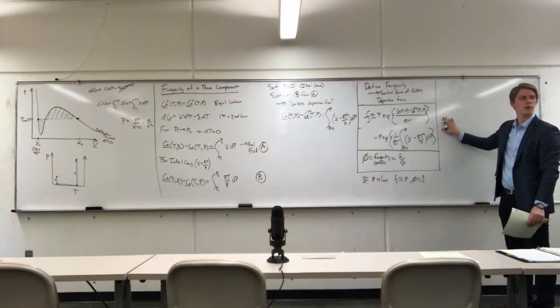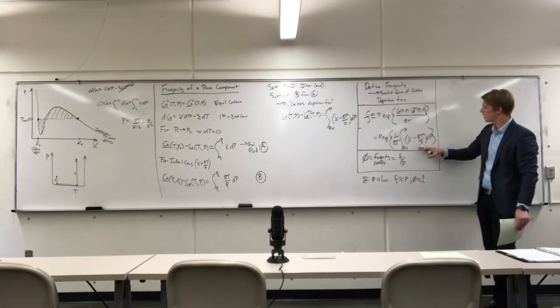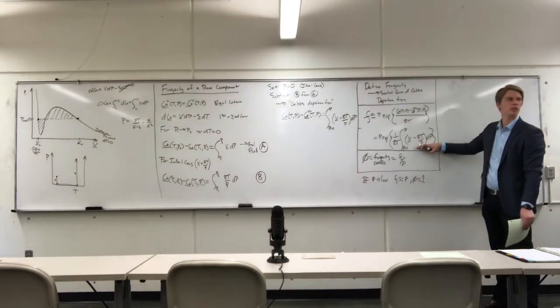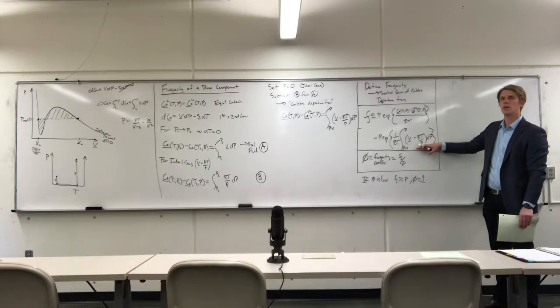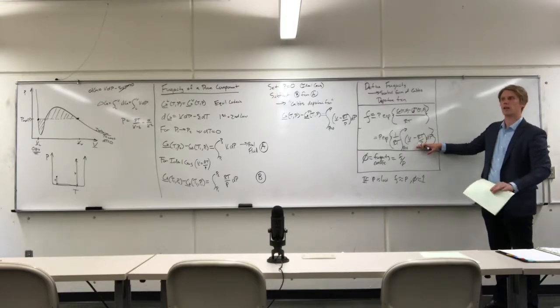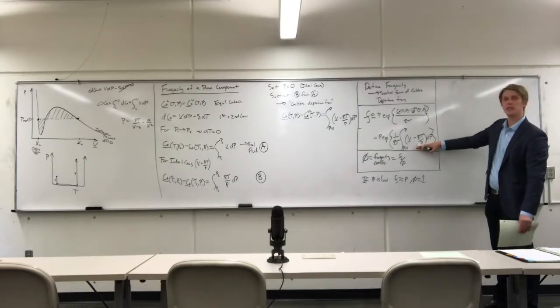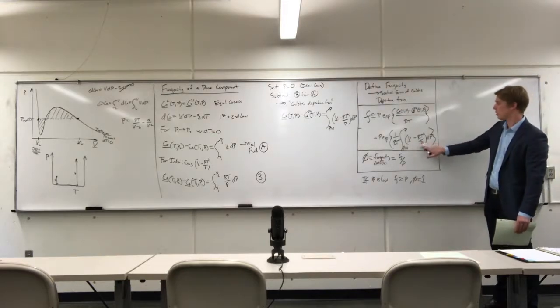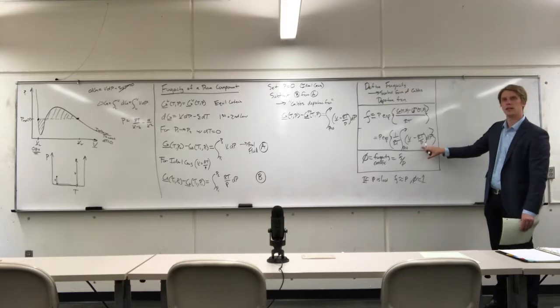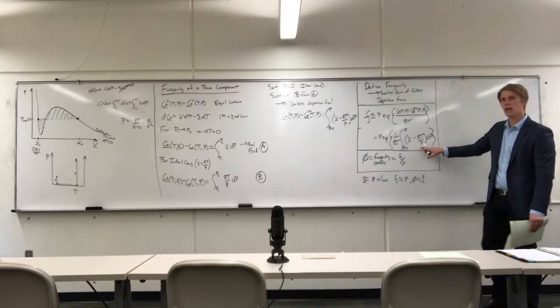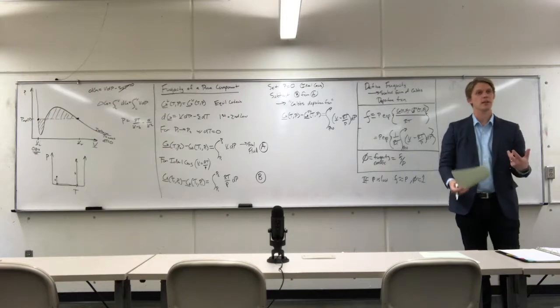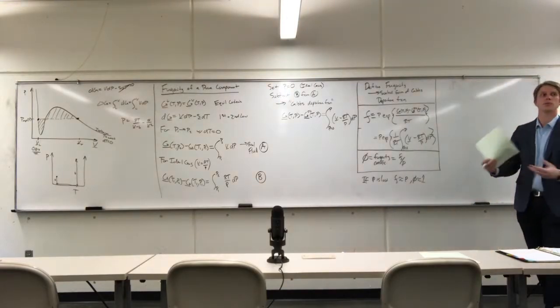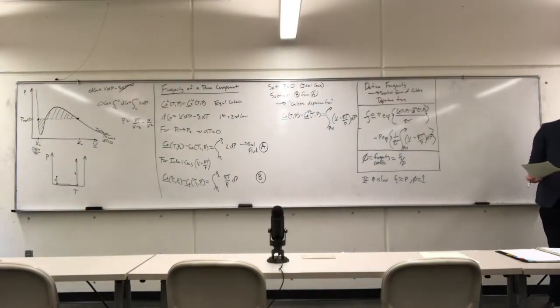The question here is why fugacity? Why bother? Well, the main reason is that a lot of the unpleasant property changes that we experience also follow the behavior that an ideal gas does. So these issues here of infinite entropy when you go to zero pressure, that's captured all within the ideal gas state. Another good reason is that a lot of the calculations that we do, ideal gas calculations, are assumed to be something that everyone who knows thermodynamics should be able to handle. And for the most part, ideal gas calculations are relatively straightforward.